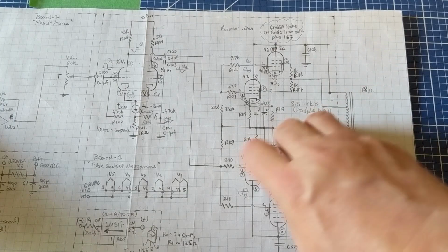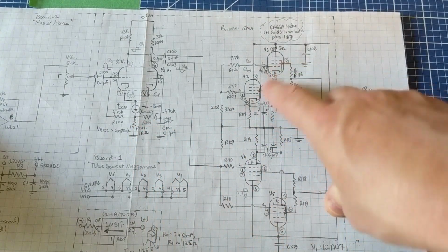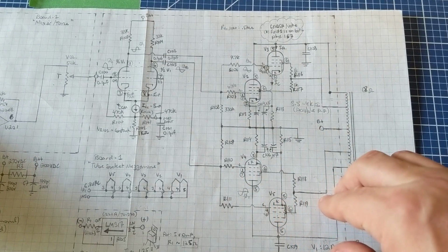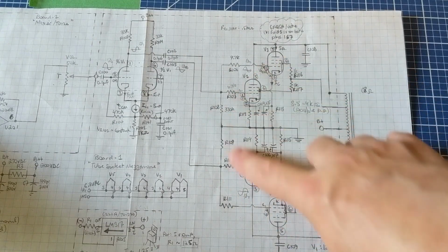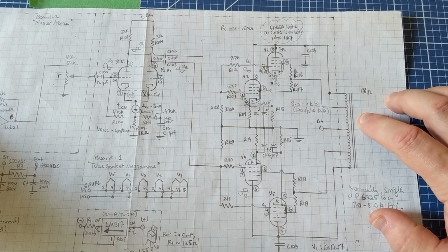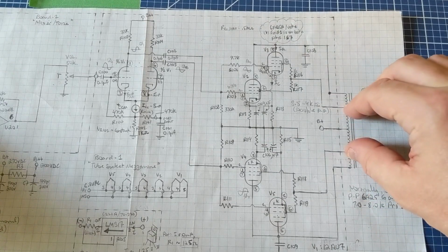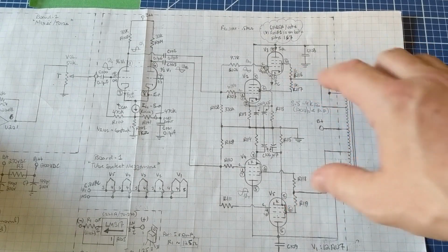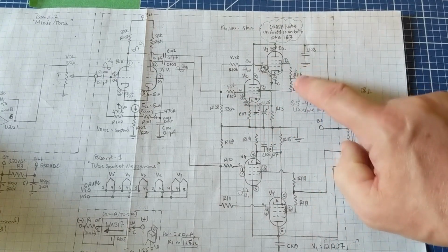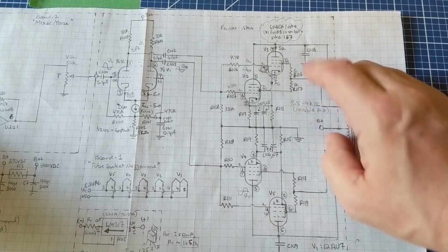It shows the phase inverter coupled into the four-tube push-pull output stage, and all of the passives surrounding that. This is the output transformer that we've seen in a previous episode. It has 40% screen taps on the primary, so those feed back into the upper and lower tubes through 1K resistors to provide a little bit of separation between tubes for screen biasing.